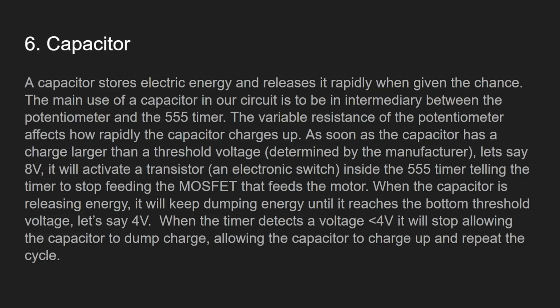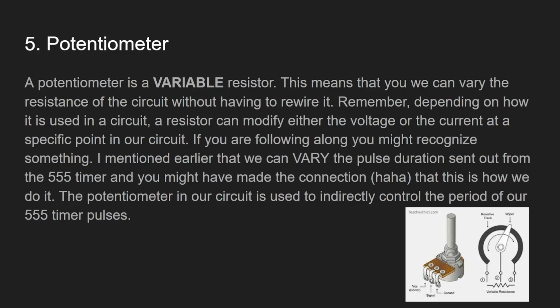So if half the time you're applying 12 volts and half the time you're applying 0 volts, it will run as if it is at 6 volts.